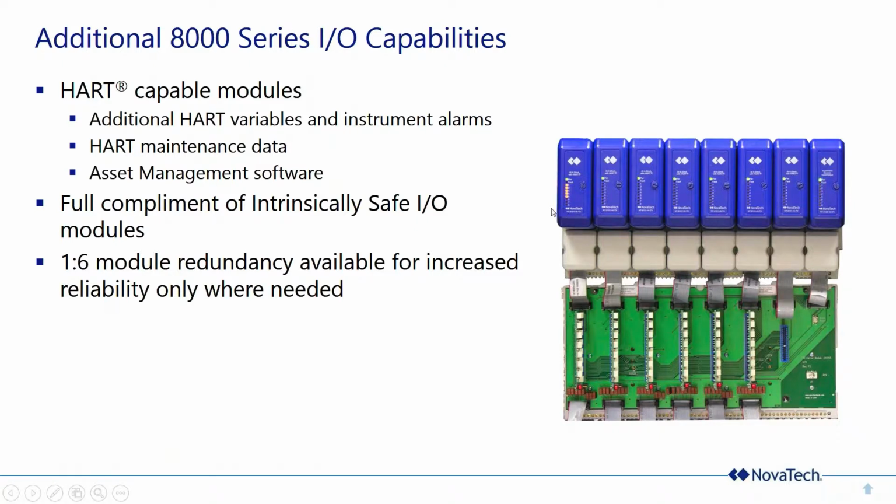Module 7 has now replaced module 1, but as far as the control system is concerned, other than alarms and status indications, none of your application programs know any different. And the switching is so fast that on any point on the module that had not failed, it doesn't interrupt your operations at all. The heart signals ride right through it. You send someone out to the field, they replace the module, and they push a switch, I believe that's it there, on the card, and that signals the EBIM that they're ready to swap back. The EBIM reverses things and swaps back.